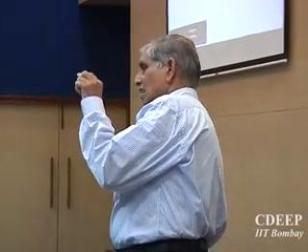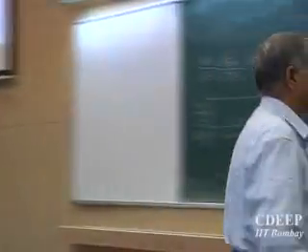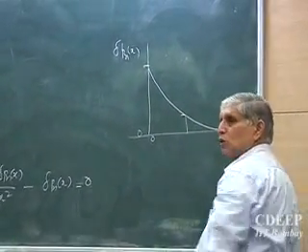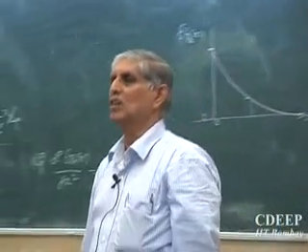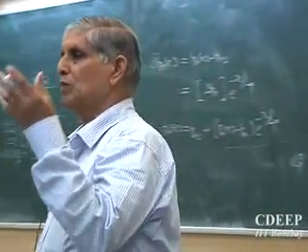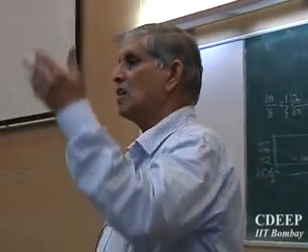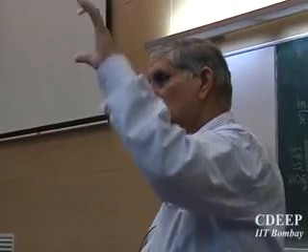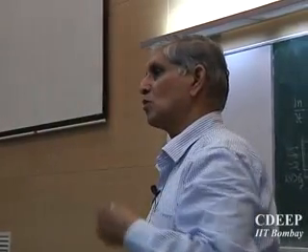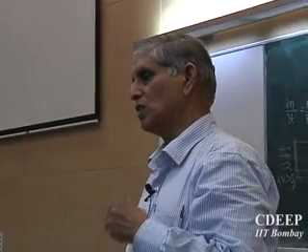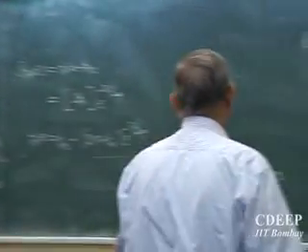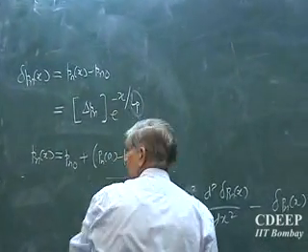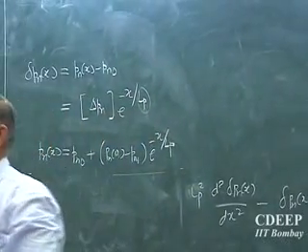That's the characteristic length. Beyond that, you can see from here, if I put a 66% value somewhere here, you are anyway coming closer to Pno. So the stronger term, the diffusion term, becomes of lower dominance. It is the recombination which will finally take it back to Pno. But in between, both of them are trying to pull it down so that they go to the equilibrium value. This is most important. The effect of diffusion as well as recombination is taken care of through which term?